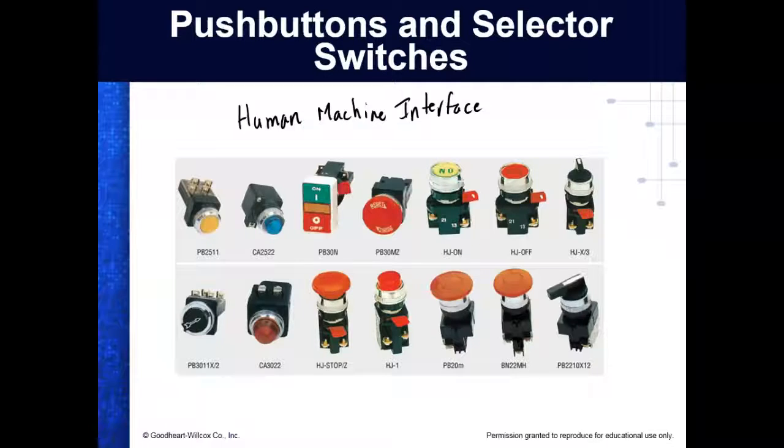So we call these HMI panels. These are the touchscreen panels, kind of like the touchscreen on your cell phone, except they don't use capacitive like these do. These usually use what we call resistive film because they don't want you to accidentally hit them, right? So you literally have to push in on them almost like a real push button. And a lot of it is going to simulate them.